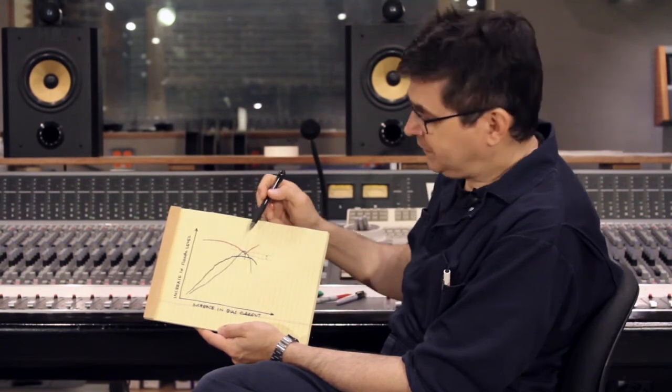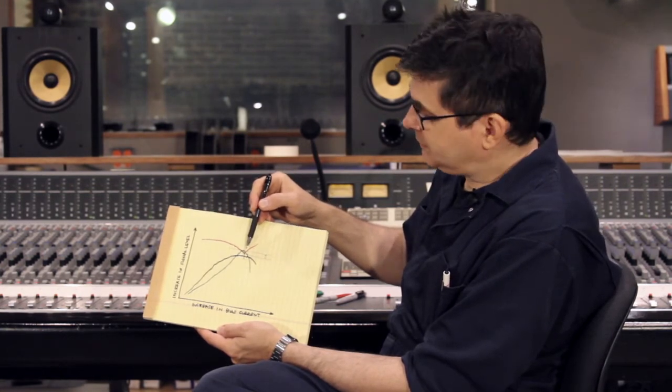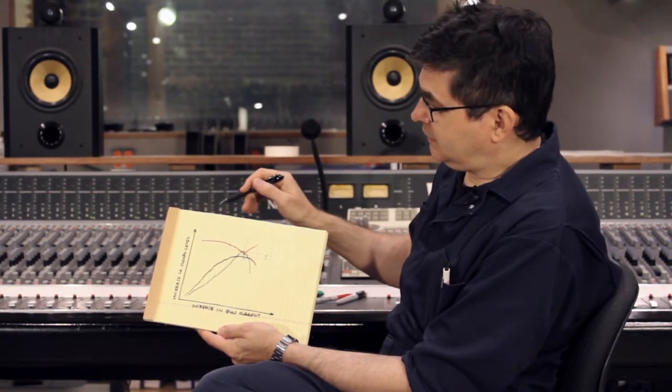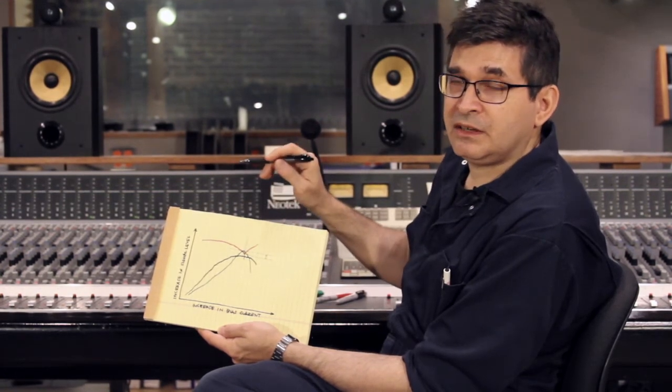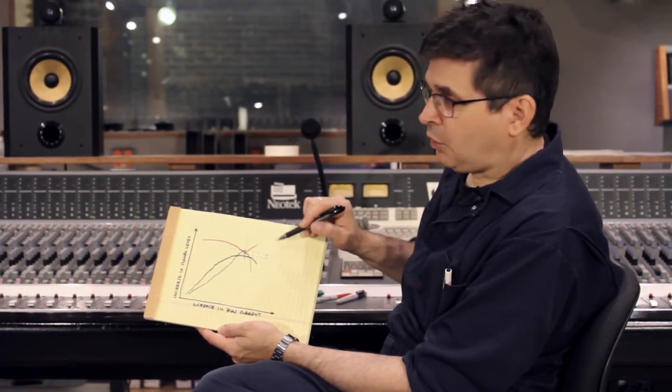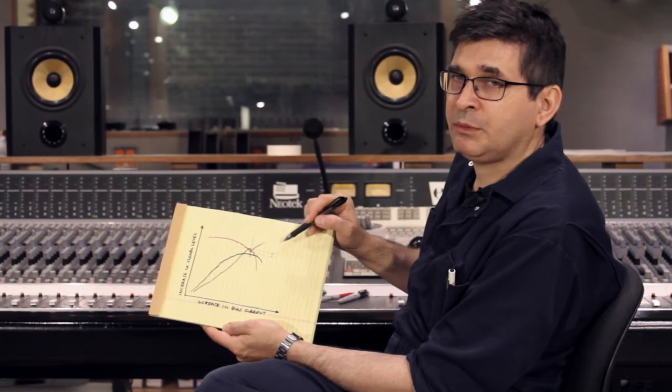and you will have found the optimum bias point for that tape. And what you can do then is, having found the optimum bias point, you can then plug in a 10 kilohertz tone or 20 kilohertz tone and adjust the bias down until that signal is at a peak, and record those two numbers, and you will have found your personal overbias for optimum noise and distortion on your machine with that tape formulation.